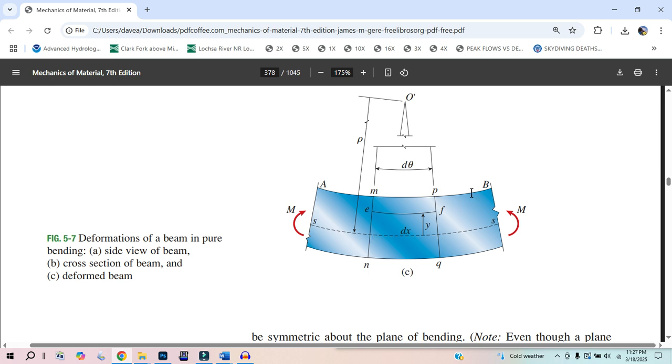So you're going to get a force that's big up here, and it's going to taper to zero. Then down here, these are going to be your tensions. Your tension is going to be the biggest down here, with an arrow that way and an arrow this way. At halfway, it's just going to be half the force required to stretch this out. That is the fundamentals of material mechanics: if you have stretched something, you must have applied those forces on those areas. That's the relationship between change in length and force applied.